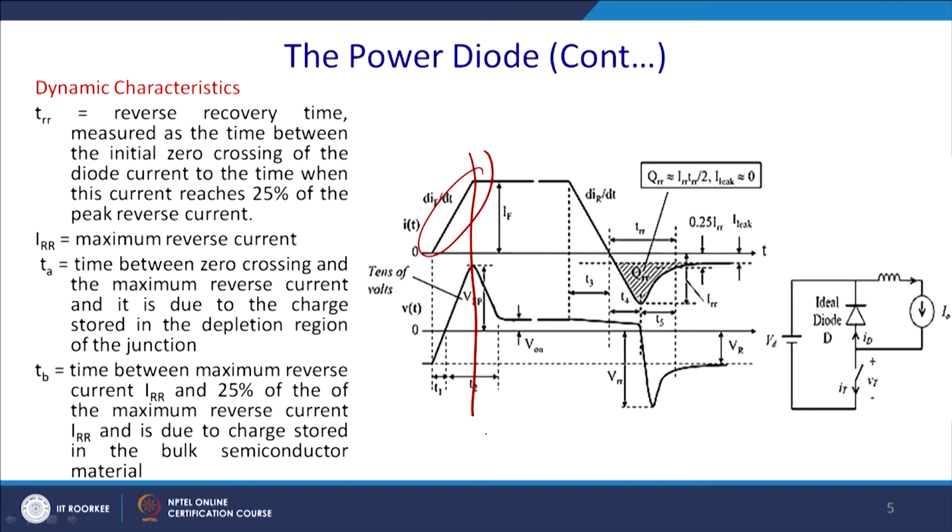Thereafter, once it reaches the peak voltage, the voltage will fall, until the voltage falls down to its forward blocking voltage, let us say 0.7 or 0.8 volt or more, depending on the amount of the depletion layer. This time is called T2. By that time the current will reach its saturated value, whatever the rated current is, and it will continue thereafter.